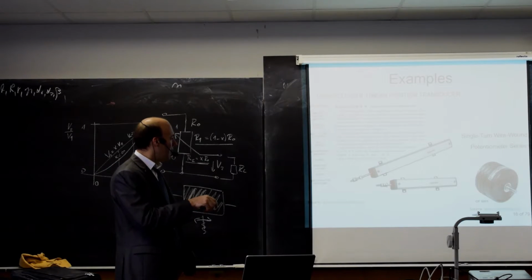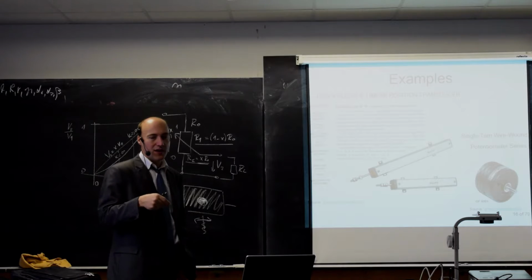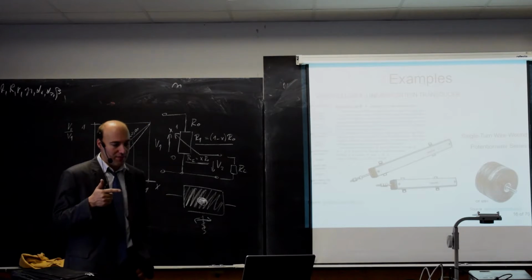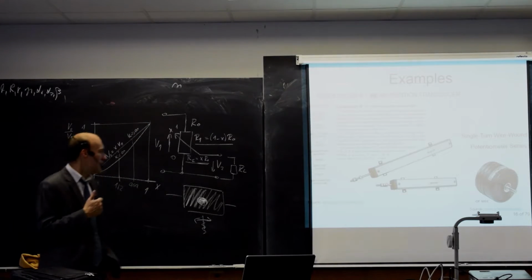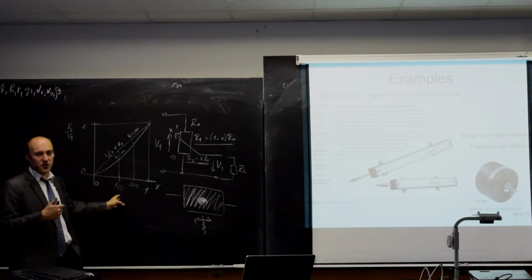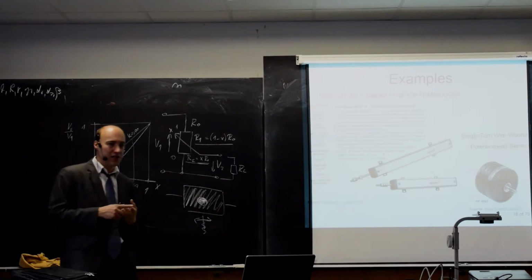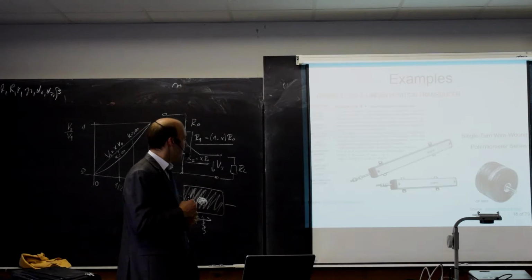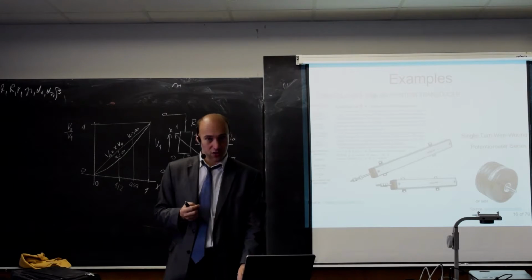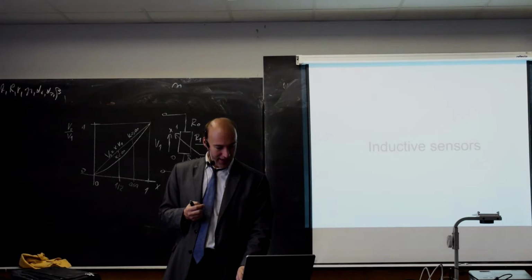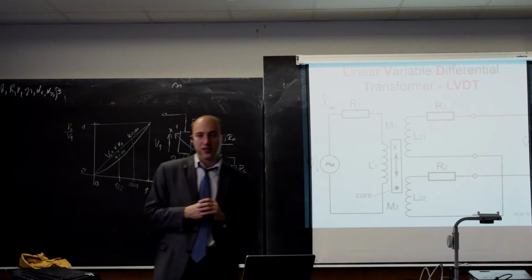The properties of angular sensors are the same as for linear sensors. So you again need to watch for maximum voltage, maximum current, and it has exactly the same properties as the linear one. It means a specific position for relative error, absolute error, and there will always be a difference between the measured signal and the real voltage that I have from the sensor. Any questions related to resistive sensors? Okay, good. So now we'll be talking about inductive sensors.